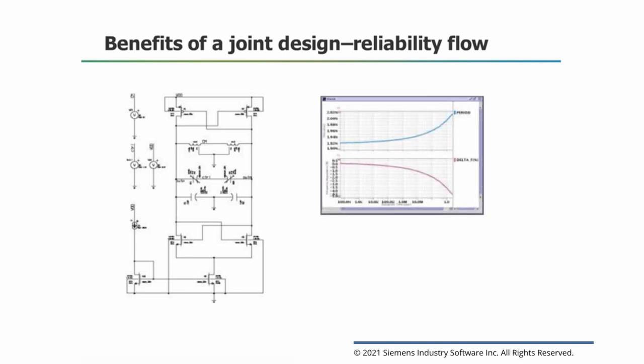This example shows how the operating frequency of a CMOS oscillator degrades over time. The absolute period and the relative degradation in percentage of the frequency are shown in the upper and lower plots respectively. The x-axis is the time in years on a logarithmic scale. The frequency is degraded by nearly 5% after 1 year of operation.